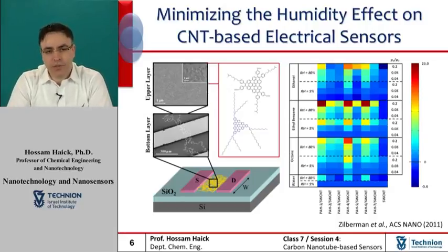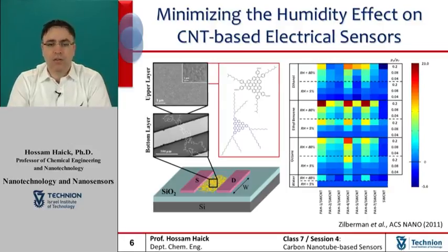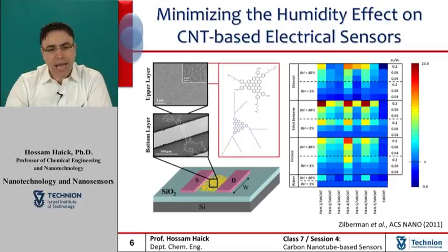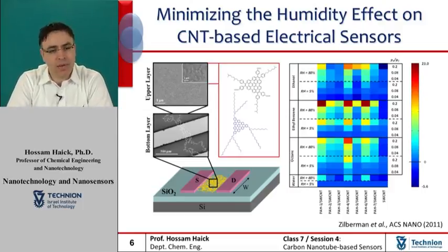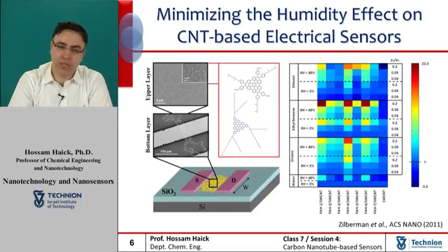In most cases, good discrimination between the volatile organic compounds and the water signals is obtained. A cross-reactive array that is based on the polycyclic aromatic hydrocarbon and the carbon nanotube sensors is provided, and DFA and PLS recognition methods exhibit discrimination between the various VOCs, or volatile organic compounds, in mixtures with either 5% relative humidity or 80% relative humidity.